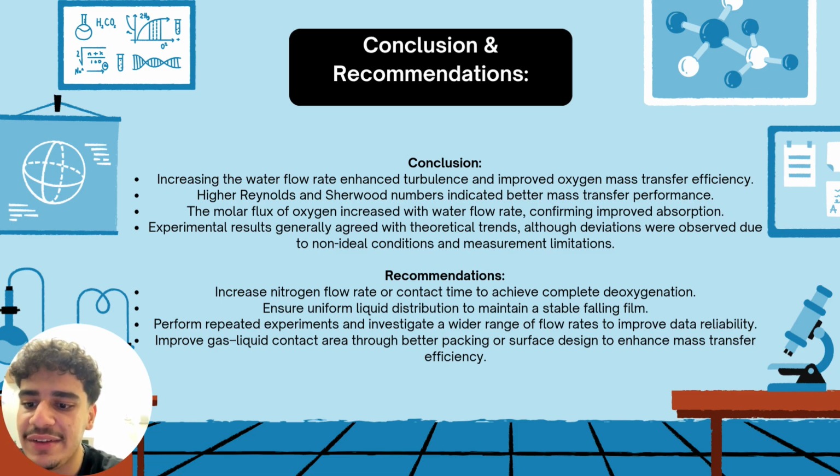And for the recommendations, increase nitrogen flow rate or contact time to achieve complete deoxygenation. Ensure uniform liquid distribution to maintain a stable falling film. Perform repeated experiments and investigate a wider range of flow rates to improve data reliability. Improve gas liquid contact area through better packing or surface design to enhance mass transfer efficiency.